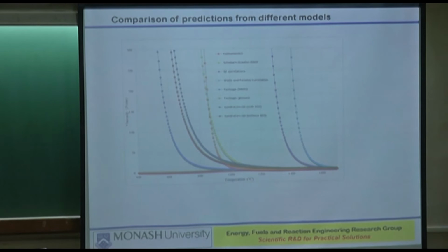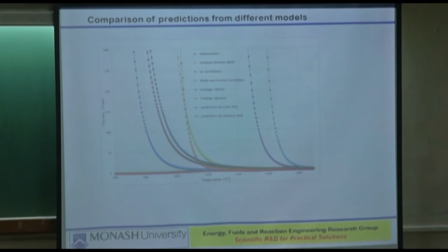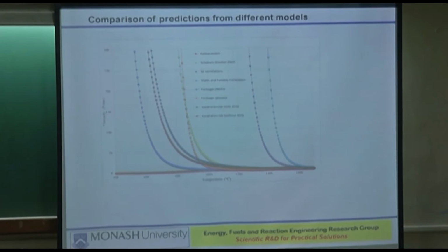Those measurements can be done in either a reducing environment or an oxidizing environment. In a reducing environment, the 4 temperatures are lower compared to an oxidizing environment, which means that in a gasifier, where you have a reducing environment, the ash will melt at a lower temperature than inside a PF fired combustor. That is fact.